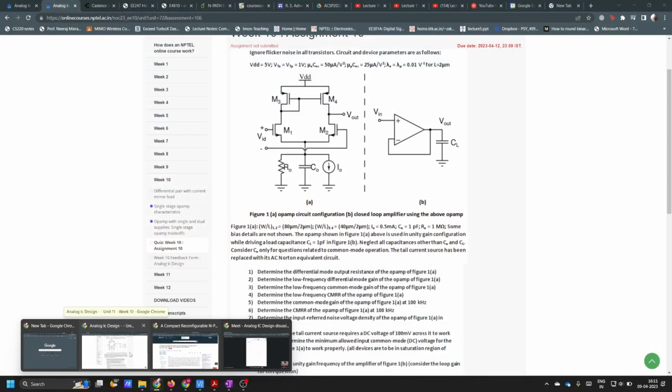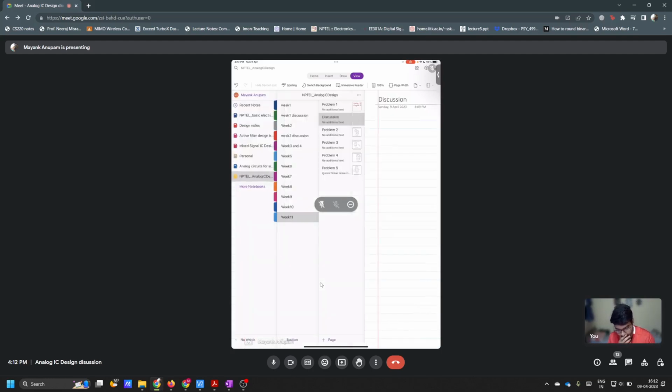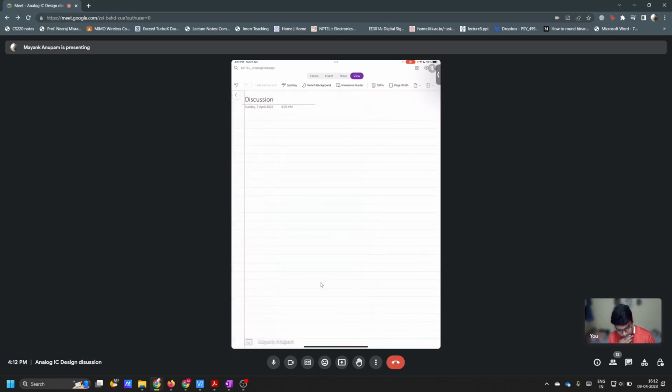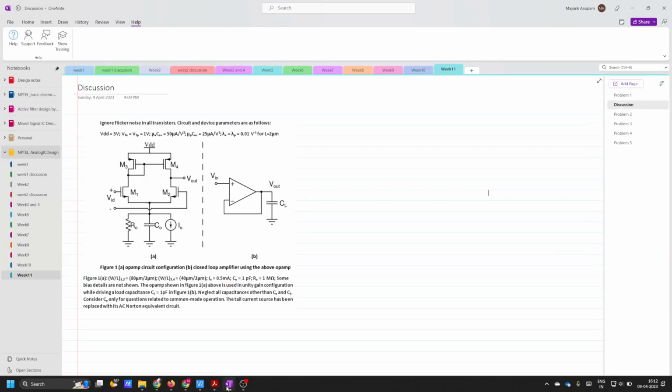In an op amp, there will be the tail current source M naught, no, sir. Yeah, correct. That will be at virtual ground in differential mode. So even if the capacitor is present, it will not affect the pole or zero of the total op amp. Yeah, correct. If it is a fully differential op amp, it will not affect, only in the differential case. In the common mode case, it will affect. Is that clear? Yes, sir.